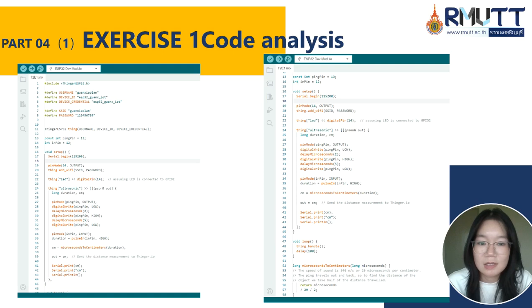GPIO14. The code first configures the Wi-Fi connection and the IoT platform authentication information. It initializes the hardware in setup and loads the cloud control interface, where the scene automatic ranging handles distance measurements, and the scene LED resource provides remote on-off control of the LED.